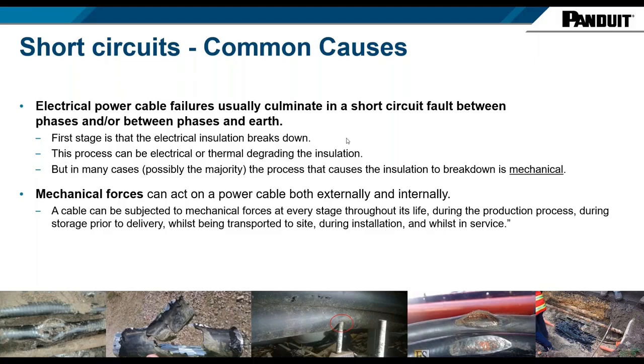The next image, where you can see the cables are worn away, is actually taken from an oil and gas platform in the North Sea, where the cables went from one platform over to another, floating platforms. And obviously those platforms move in relation to each other, and the cables were just laid and looped. And eventually, a matter of weeks actually, the insulation just wore through, and a short circuit brought both rigs, the main rig and the support rig, to a standstill for 48 hours.